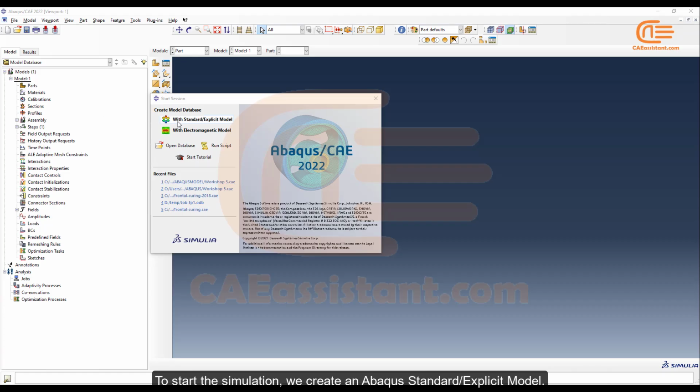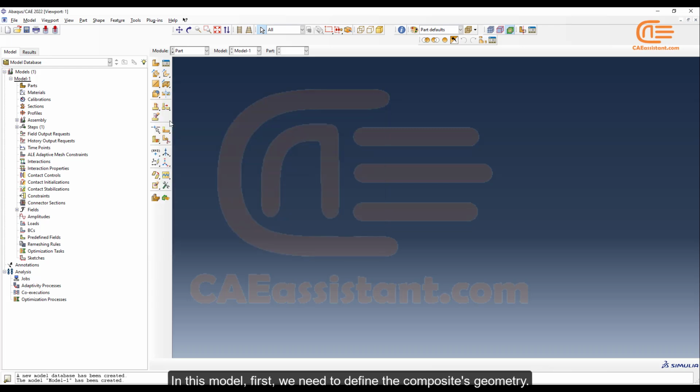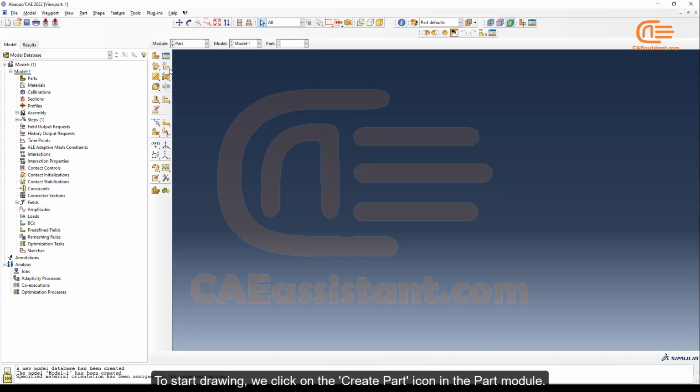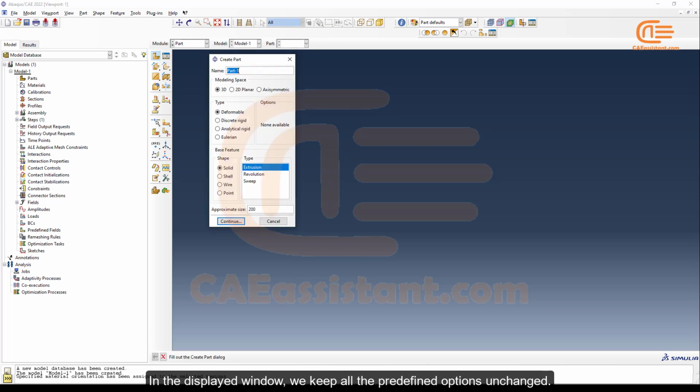To start the simulation, we create an Abaqus standard explicit model. In this model, first we need to define the composite's geometry. To reduce the computational costs, we have modeled only the analytical domain with symmetric boundary conditions applied appropriately. To start drawing, we click on the Create Part icon in the Part module. In the displayed window, we keep all the predefined options unchanged.